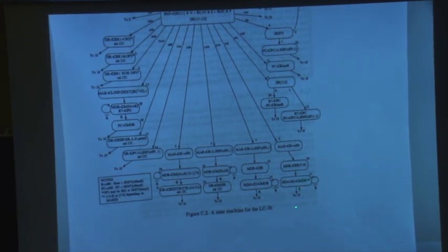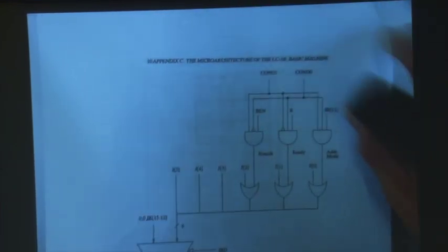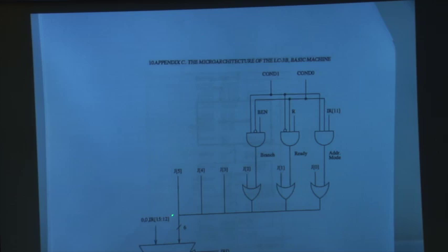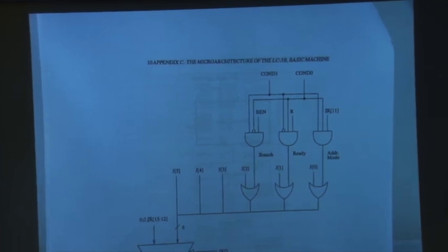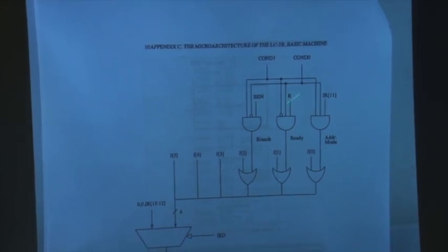Well, the reason that this is 19 is because you cannot do this conditional thing to state 18, right? If your current state is state 17, and you're dependent on the R bit of memory, your next state encoding has to be state 19, right? If this R bit is not set, you stay in state 17. If your R bit is set, your state should be 19, right? So that's why that state is encoded as 19. Does that make sense?